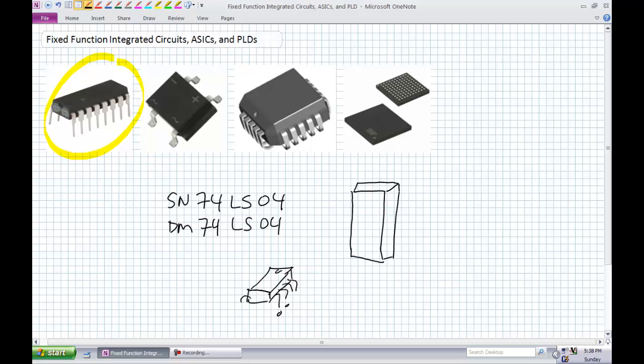He had placed these things in the holes rather forcefully, and all of them went in except for this one. It rolled underneath itself. He had the whole circuit set up correctly, and that chip looked like it was inside there. Always look at these things from the side. It took us a while to figure that out, but we had a good laugh about it after a good hour or so troubleshooting it. Actually, not an hour, but I thought that was a pretty good point there. Make sure you look at these things from the side too.